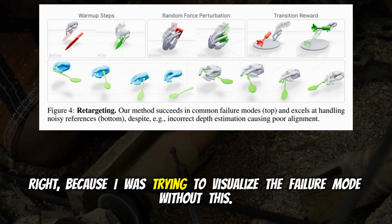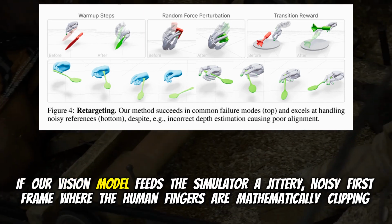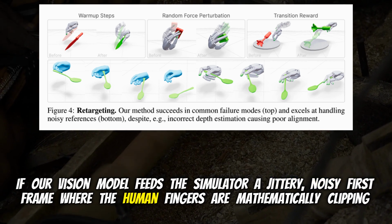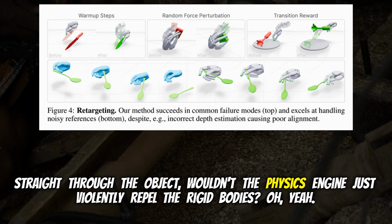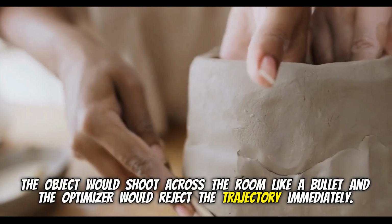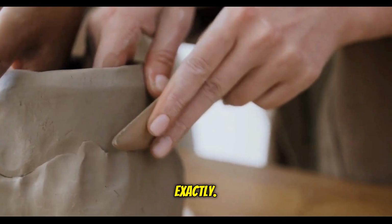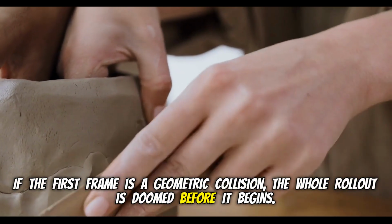Right, because I was trying to visualize the failure mode without this. If our vision model feeds the simulator a jittery, noisy first frame where the human fingers are mathematically clipping straight through the object, wouldn't the physics engine just violently repel the rigid bodies? Oh, yeah. The object would shoot across the room like a bullet, and the optimizer would reject the trajectory immediately. So that phenomenon is exactly what the warm-up steps prevent. Exactly. If the first frame is a geometric collision, the whole rollout is doomed before it begins.